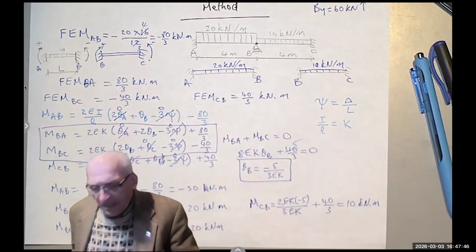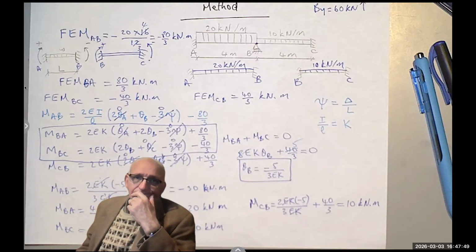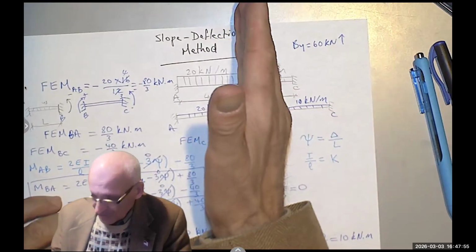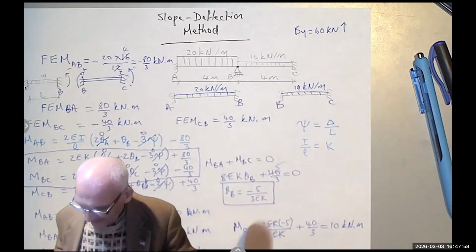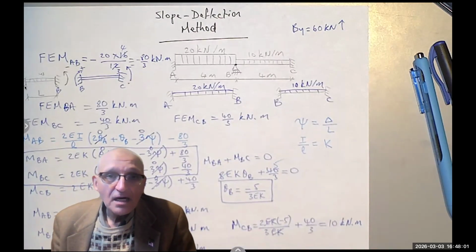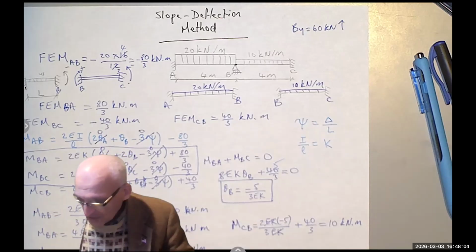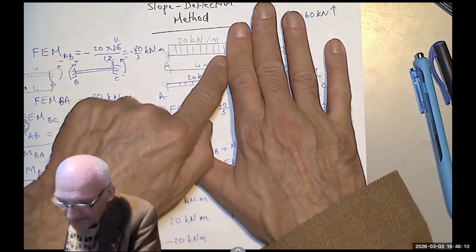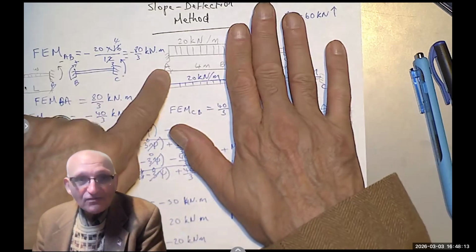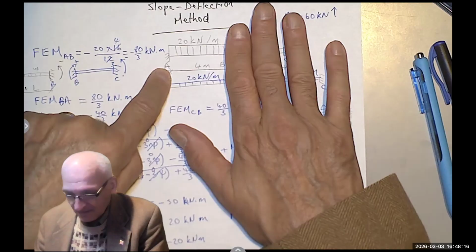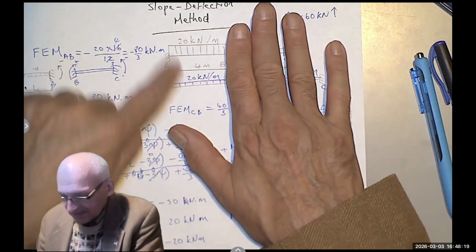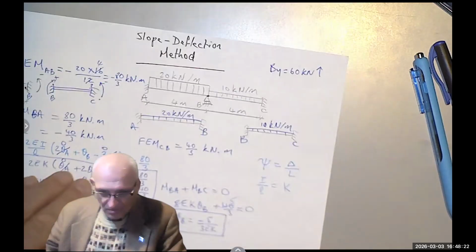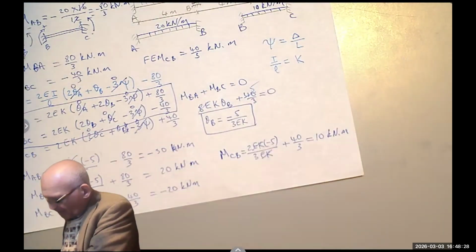Okay. I still don't know the vertical reactions. So what do I do? Now I'm going to take this beam, or this part of the beam. Notice I know the moment at B. The moment at B is the 20 kilonewton meter. So if I take this portion and calculate the moment at B, knowing its magnitude, I can solve for AY. Of course, I have a moment here, a moment there, distributed load, and a reaction. So I'll get a piece of paper to continue the problem.